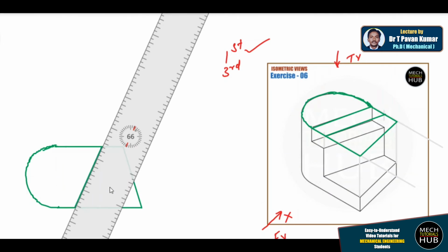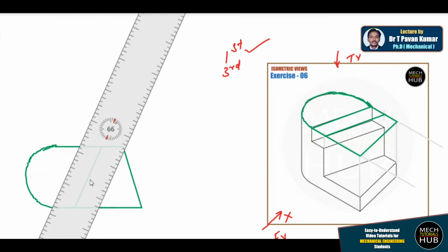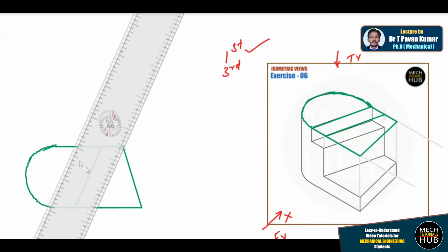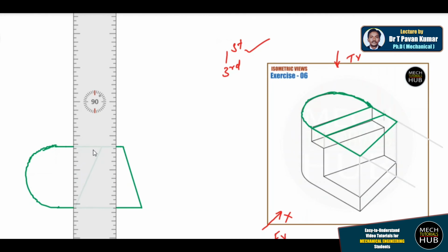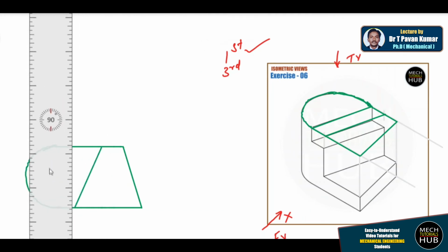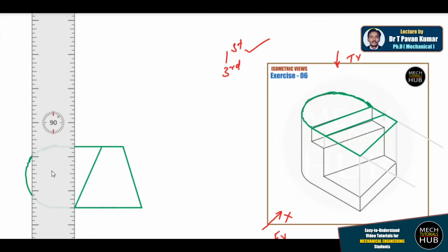You will be given all the dimensions in the question, but just to make you understand, I'm doing all the stuff. And before drawing one more parallel line, align your drafter to 90 degrees where these 2 points should be in contact actually.